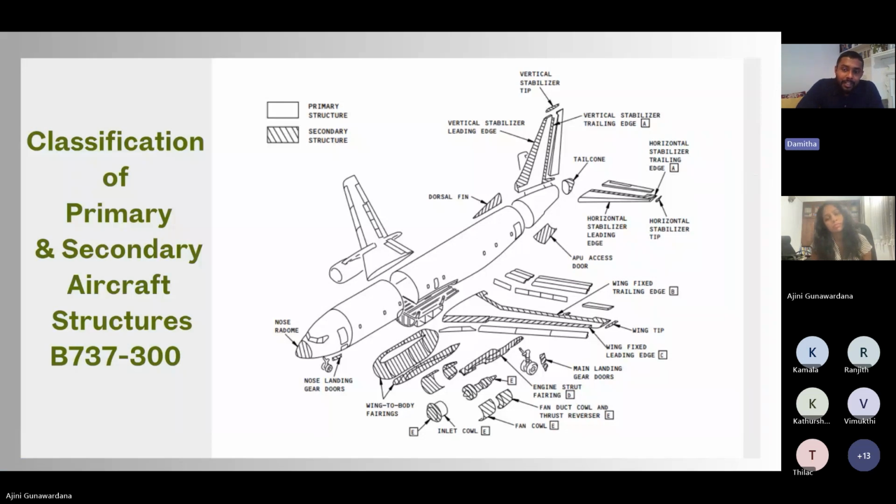The primary structures are the majority, at least on the outside of the aircraft. All these primary structures need to be able to withstand cyclic pressure loading and the vibrations and maybe a harsh landing. All these things need to be taken into account when you are doing aircraft structures, which is a very dense subject.